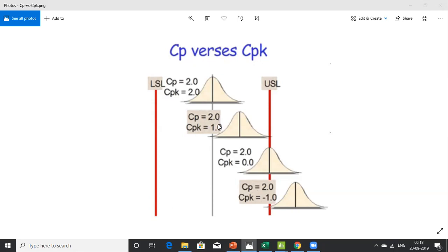And there's a difference. So if you are measuring only capability, the first part, I assume the process is capable, which is true to some extent. However, the average is way above the central tendency of the distribution. So this is what the CPK will help you to identify: whether my process is doing well within the specification limit, as well as whether it is close to the average or the median.